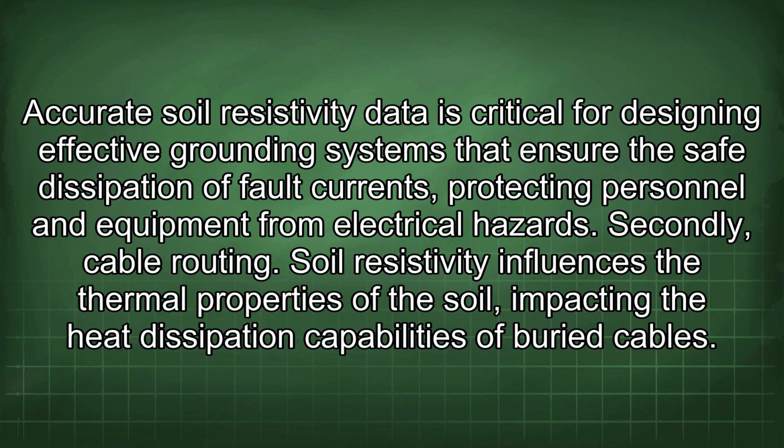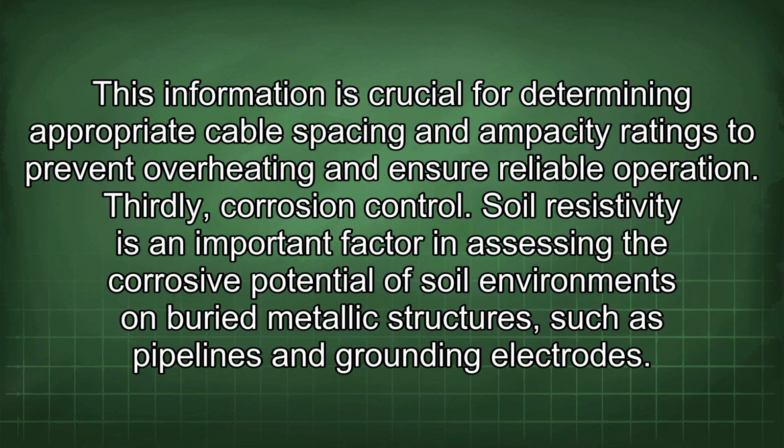Secondly, cable routing. Soil resistivity influences the thermal properties of the soil, impacting the heat dissipation capabilities of buried cables. This information is crucial for determining appropriate cable spacing and ampacity ratings to prevent overheating and ensure reliable operation.